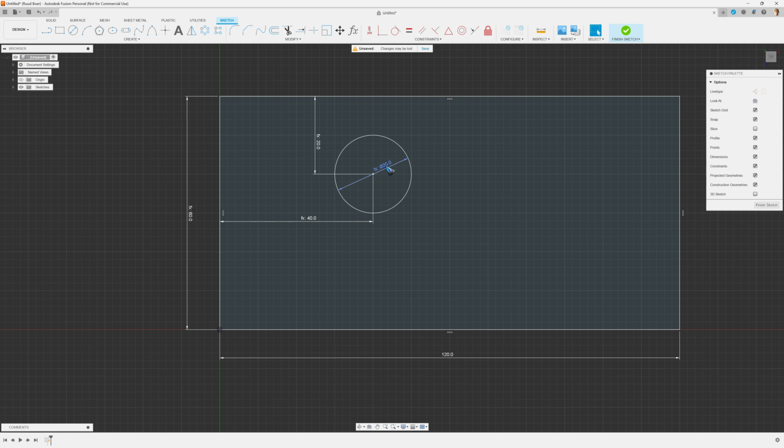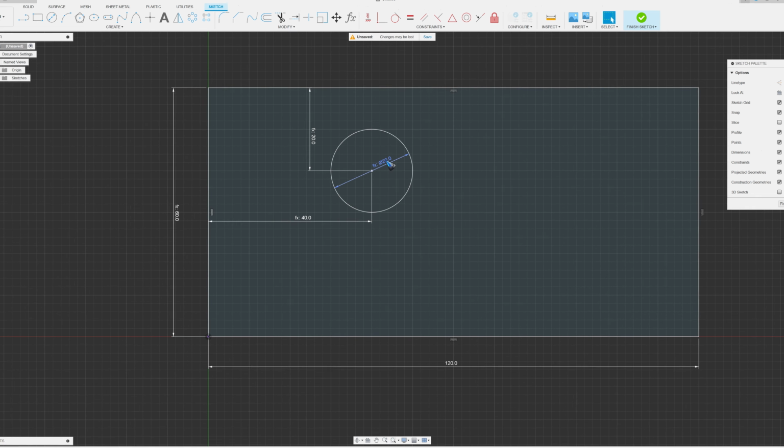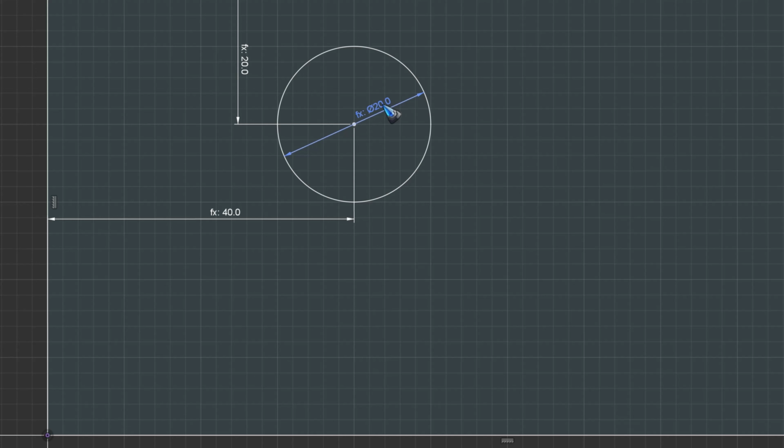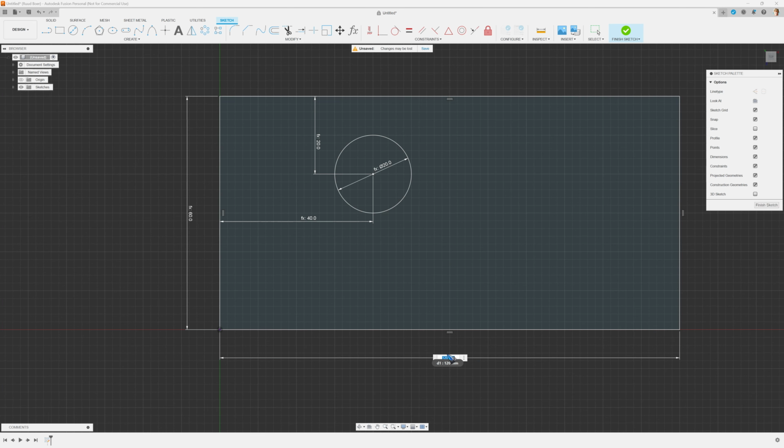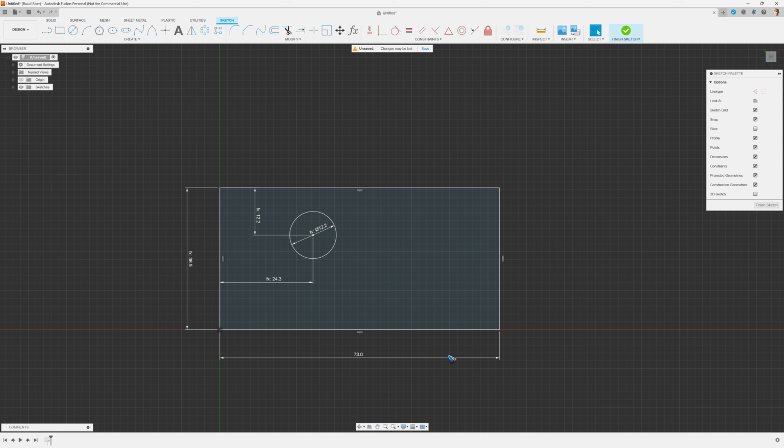Also this circle, as you can see, I already put functions inside. Let's see what is in this diameter over here. It is D2 divided by 3, and also the distance from the sides, they are functions, so that means that whatever I type in over here, even a strange number like 73, everything is neatly recalculated, and this is the big benefit of using functions inside dimensions.